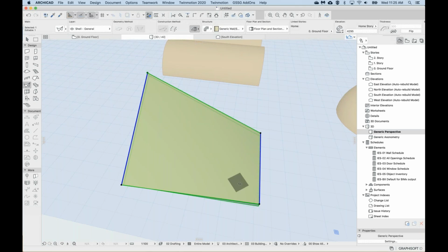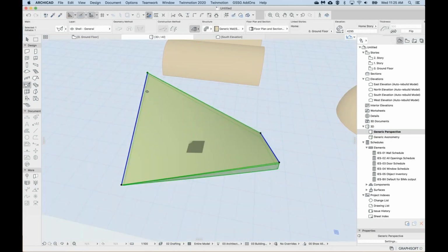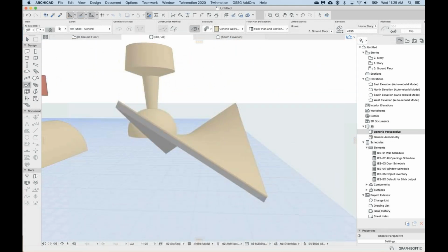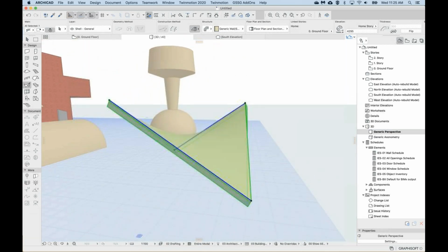And we're going to do the same, but on the diagonal corner. So the corner diagonally opposite, we're going to click this node, and we're going to do the same. We're going to drag that point up on the Y axis and click. So we'll just move 2 points on opposite corners up. And so now it looks like a parabolic roof. So it's a parabolic curve. So kind of like maybe a sunshade, a similar type of tent structure.